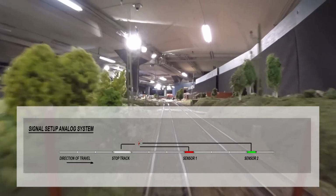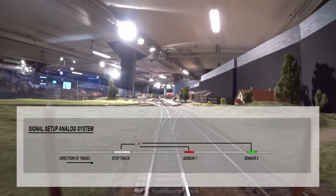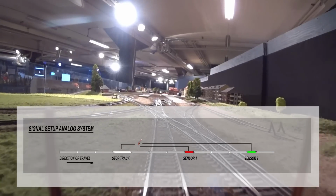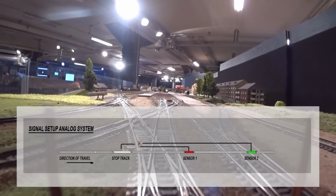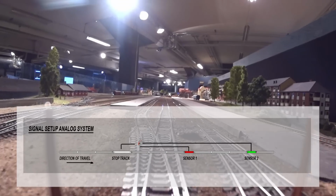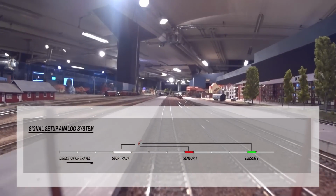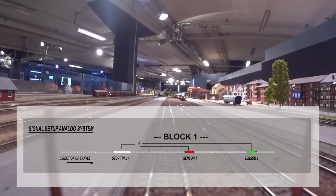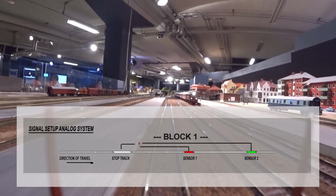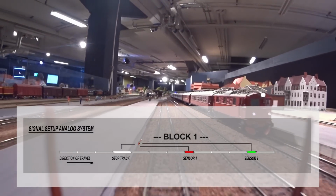Alright, so here's the typical setup for an analog system. You see the direction of travel for the trains. It first arrives at a stop track, which is an isolated track section connected to the signal. Then the train passes over sensor 1, which turns that signal to red and isolates that stop track, so any train following will stop on that track. Ultimately, the train will arrive at the end of the block and sensor 2, and that will give a clear signal to the signal, and it will power up the stop track.